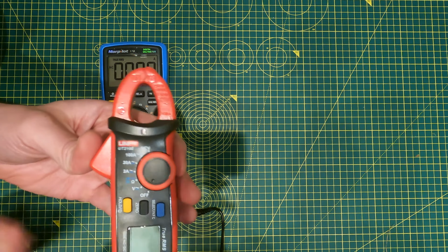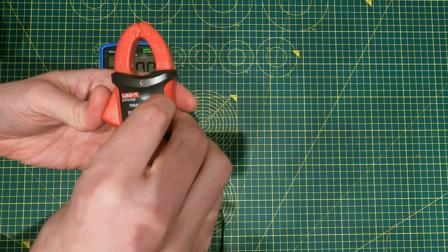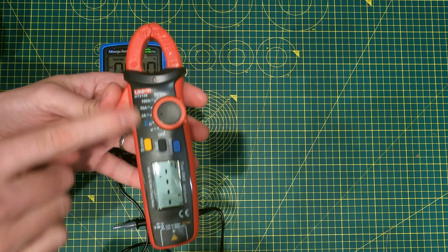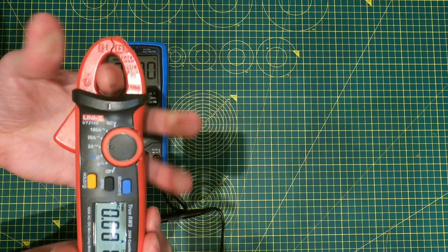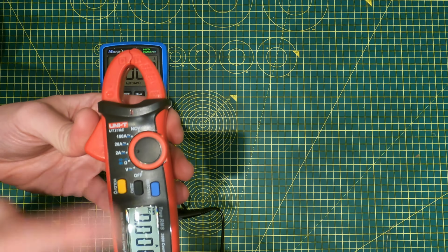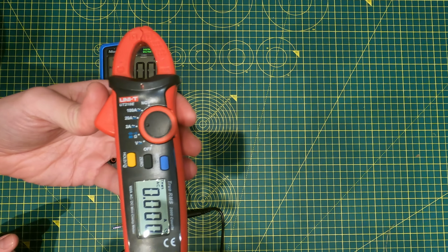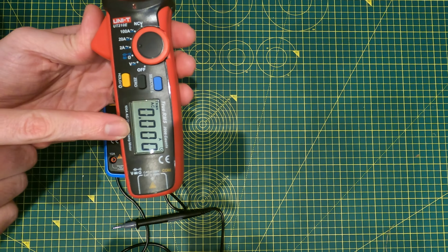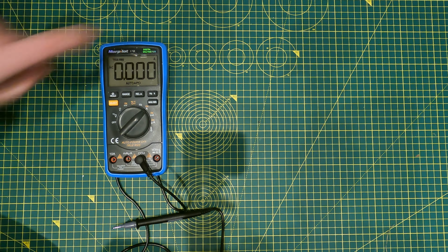All you do with the clamp meter is you clamp it over the live wire and you take your measurement. So you get your selector dial, you pop it on whatever setting is necessary, put it over the live wire. Make sure you don't put it over the live and neutral, or the electromagnetic fields will cancel each other out. And then you just take your value right there. So these are a lot safer and better to use than the multimeter.